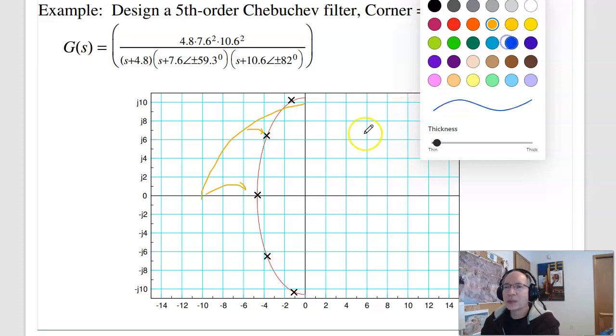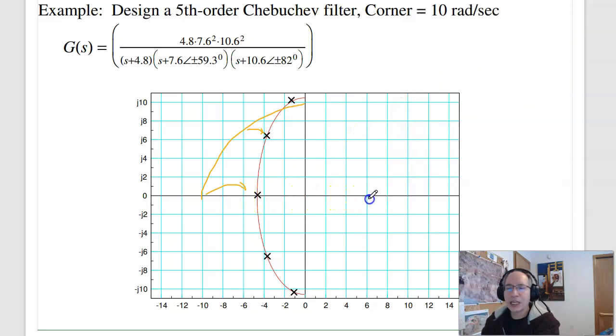you can kind of see what the gain is going to look like. At this point at DC, I'm close to this pole, I get a resonance. Then I move away from the pole, the gain drops. Then at this pole, I had another resonance, and the gain drops. Then I had another resonance, and the gain drops. And the resonances keep on getting tighter and tighter, because the real part gets smaller and smaller. That sets the bandwidth.